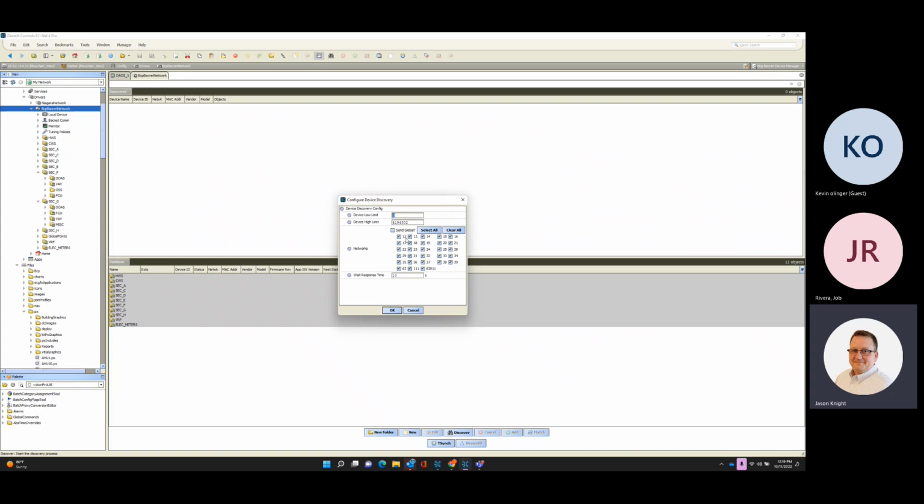And each one of these routers has to have a different subnetwork number. These subnetwork numbers we based on the last octet of the IP address that was given to us from your IT department. I have spreadsheets of all these devices with the individual physical MAC addresses. I have the device instance ID numbers recorded for your BACnet routers.